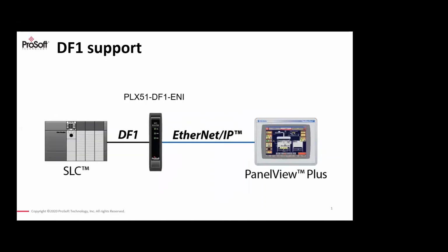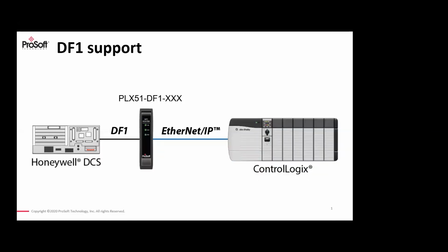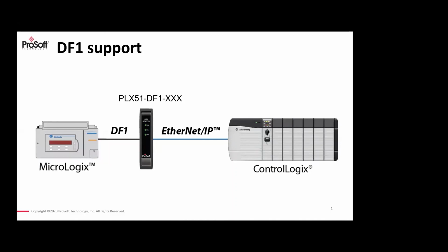You can also have direct messaging between EtherNet/IP devices and your DF1 controller. It allows you to migrate downstream from DF1 to EtherNet/IP and EtherNet/IP capable devices. And not to forget direct messaging between legacy DF1 controllers and the current EtherNet/IP for the new PLCs, of course.